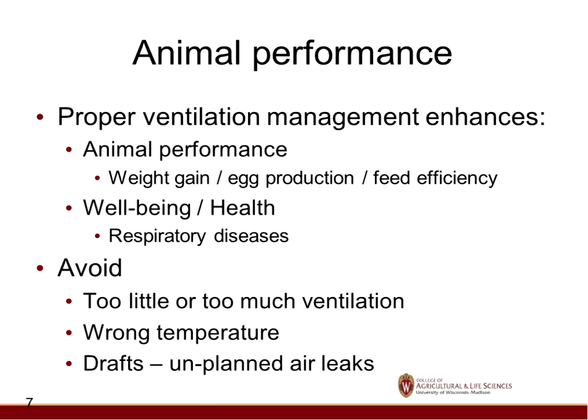But from an energy standpoint, we don't want to ventilate too much, especially if we're doing supplemental heating, and we don't want to ventilate too little because that could add heat stress for the animals. If we ventilate too much, it could add stress from the cold side too. When we're looking at the temperature of the environment, we need to make sure we have the right temperature for the age and species of animals we're housing. You're going to see when we talk about poultry and swine that as they age, the temperature goes down.